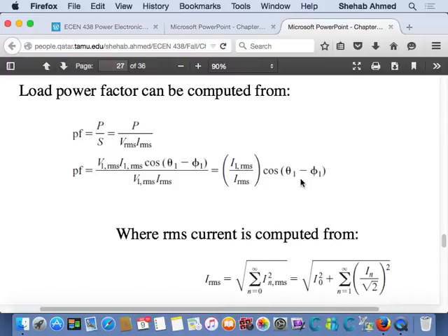Industrial consumers, they are able to control better, right? They tell RasGas, no, you cannot do this. You have to maintain your power factor, worst case, 0.95. So RasGas has to comply. If they have lots of components, motors, lots of transformers that consume a lot of reactive power, that's something they have to consider. If they have lots of power electronic systems like motor drives driving these big compressors, these are nonlinear loads, and they will make your power factor poor as well, right? So all of this stuff is your load. It contributed to poor power factor. You have to fix it, right?